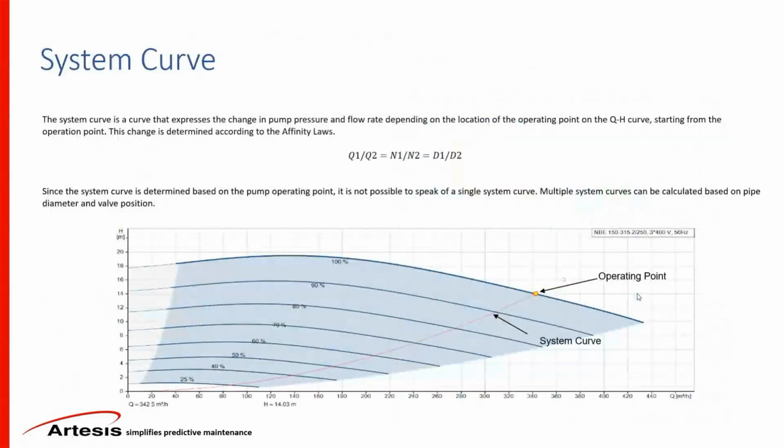And the final curve that we are going to look at is the system curve. The system curve is essentially multiple curves for different speeds. So you can create as many curves, again, with small intervals between speed changes. This will give you a best efficiency point across a variety of operation points and speed requirements for the system curve.